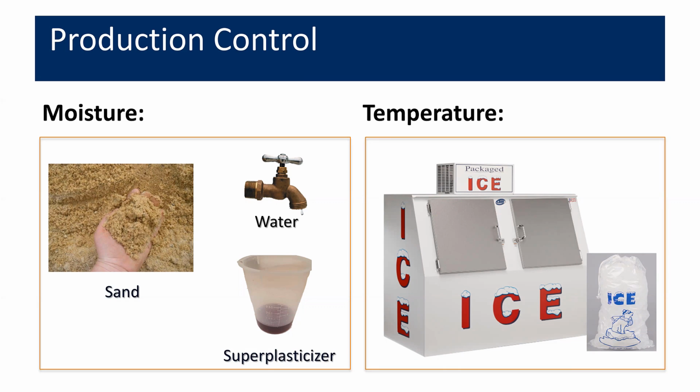The other thing that we need to be careful about in order to maintain our workability is controlling the temperature. Ideal UHPC temperatures are lower than typical concrete temperatures. Really, the target range you want to get is 50 to 80 degrees Fahrenheit in order to maximize long-term workability for most UHPC mixes. And so sometimes that requires introduction of ice as a substitute for the regular batch water.